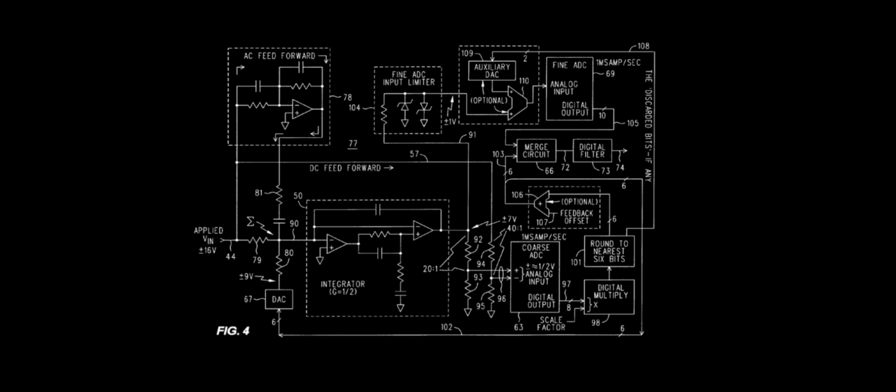A higher order modulator randomizes these errors out to a large extent, but since the Multislope 4 modulator is outwardly a simple first order system, the fine ADC could be used to add some extra granularity to the modulator output to prevent these problems. The patent also suggests that a dither signal is applied digitally to the output of the coarse ADC before it is fed into the DAC, which should help eliminate this problem.